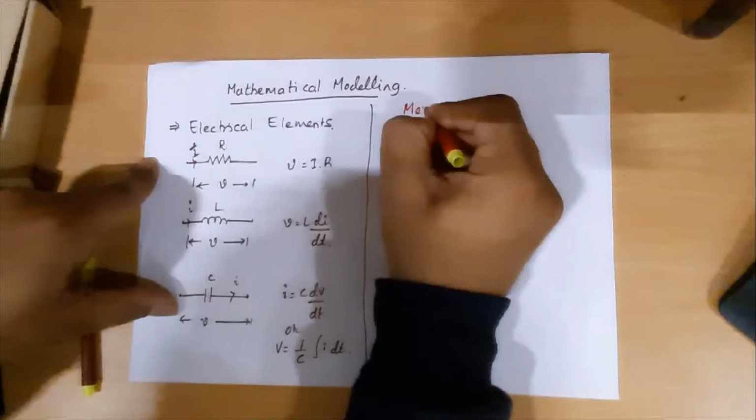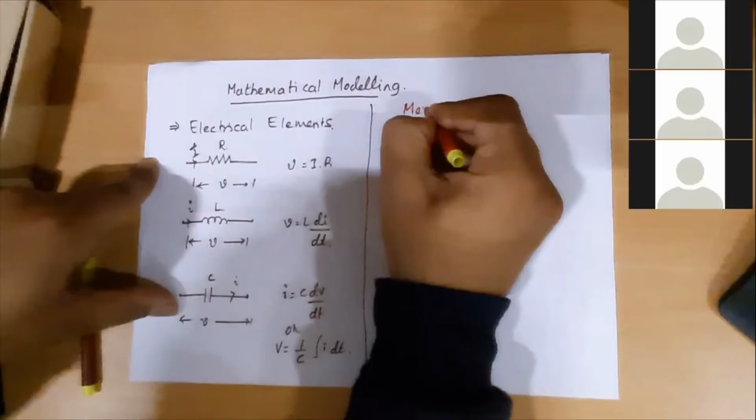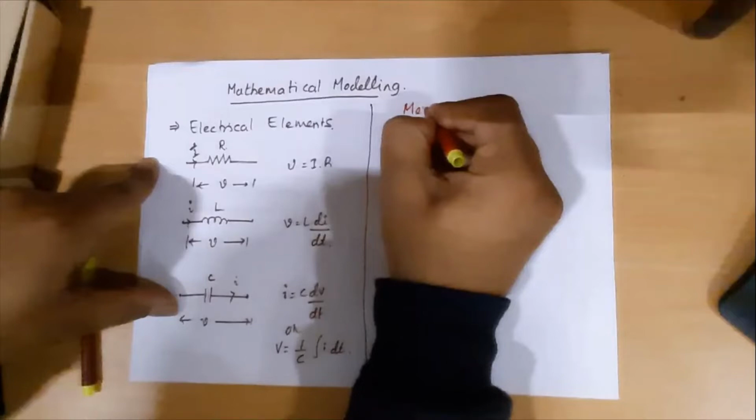So everyone knows how V equal to IR has arrived. Then for inductance, similarly, we have V is equal to L di by dt. Similarly for the capacitance, we write I equal to C dV by dt, or another definition, V equal to 1 by C integration of I dt. I have written these equations without any integration limits or without adding a function of time, just to avoid confusion. I hope it is clear for everyone, and there is a lot more to be done with these equations, which we have already done in your previous course, network analysis or electronic circuits.